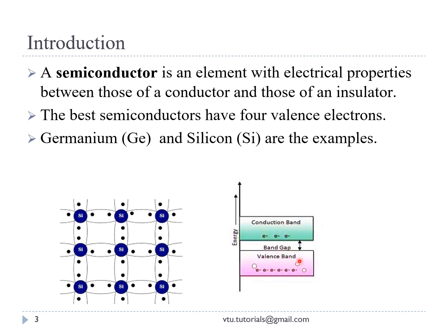In the valence band there are a large number of electrons, and in the conduction band only a few due to temperature, and hence there is low conductivity in the semiconductor. If energy is supplied to the electrons in the valence band, they will jump into the conduction band, and there will be large conduction in that material.